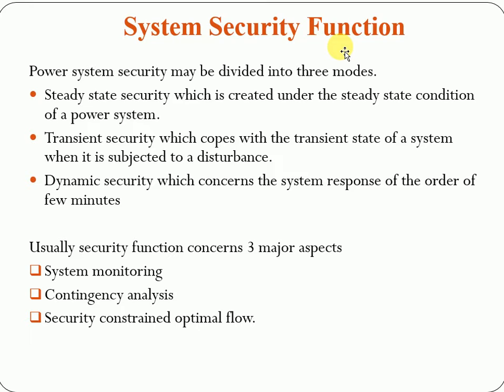In practice, all power systems can be affected by unpredictable faults and failures such as lightning strikes on transmission lines, mechanical failure in power plants, or fires in substations. In virtue that these natural phenomena are unavoidable and happen relatively frequently, all power systems should be designed to withstand them without emergency. In order to avoid blackout and wide-scale consumer disconnections, the system should be operated with a sufficient margin which can be explained in terms of two elements, reserve generation and transmission capacity.